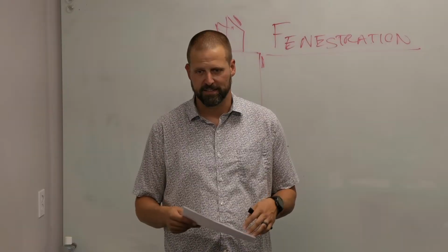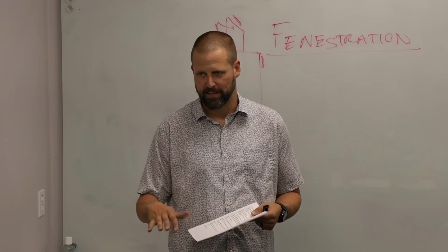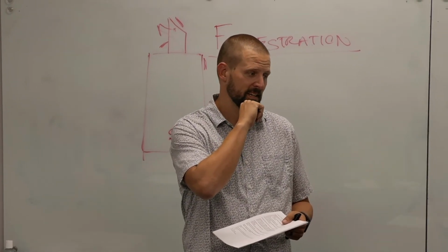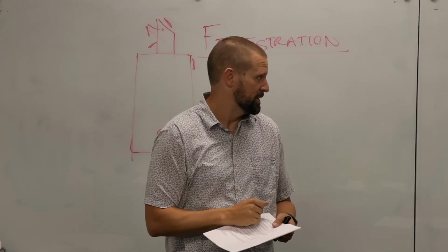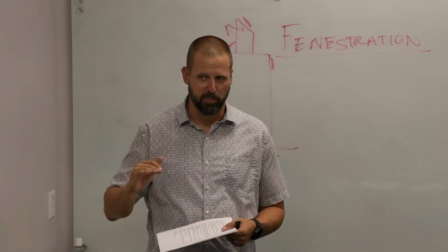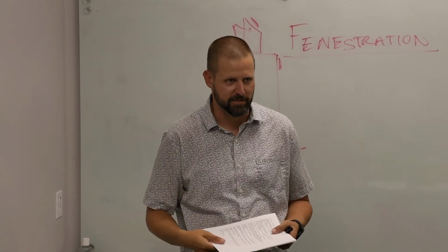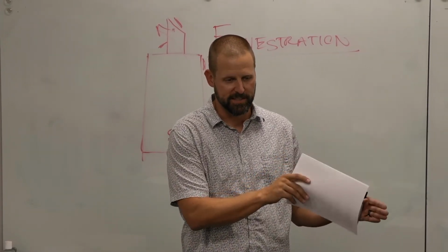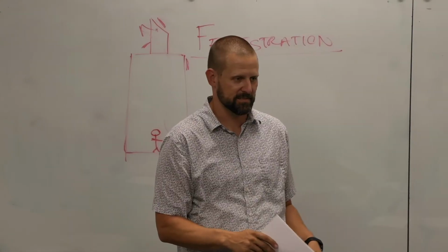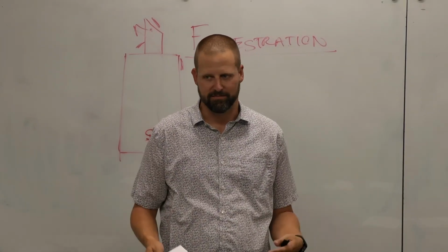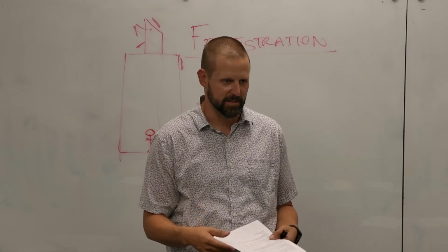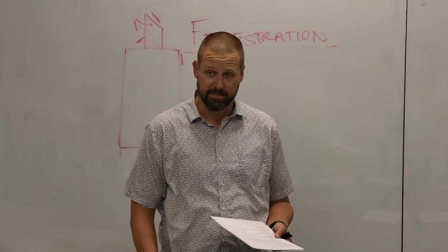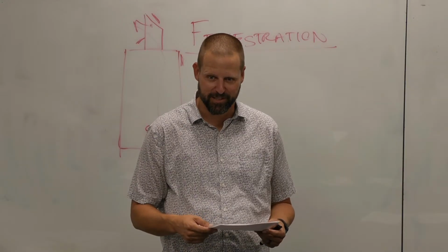Engineers have done a lot of studies saying it's at least half of that in practice. And we can get more aggressive with our designs. But the load calc software that exists generally supports the 10 to 15 BTUs a square foot. So it'll be interesting because the solutions for heating have gone up in price, in my opinion, tenfold, at least with the new technologies. So that's a rant that I won't do right now because you guys all want to get back to work or get another slice of pizza.